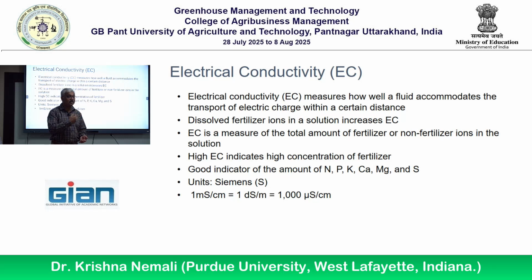in electrical conductivity. So if your water has a lot of certain non-fertilizer ions, like in this case bicarbonates, you are not only measuring the concentration of fertilizer, but you are also measuring the concentration of non-fertilizer ions in the solution. So you may think, when I say EC is good as long as EC is 1.5 or 2.0, the crop is getting all the fertilizer it wants.